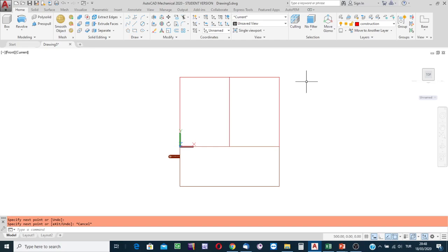For having the region, the necessary profile, to thereafter use for creating the revolve feature, in this example there will be a circle arc and straight boundaries. So I'm going to create a circle. I selected the diameter option, center point. Where is the center of the circle?